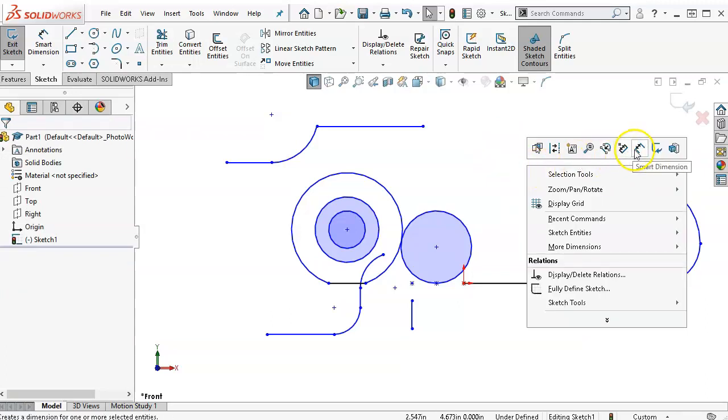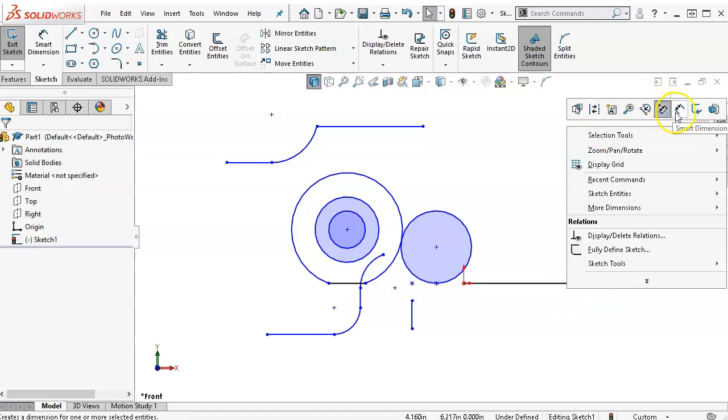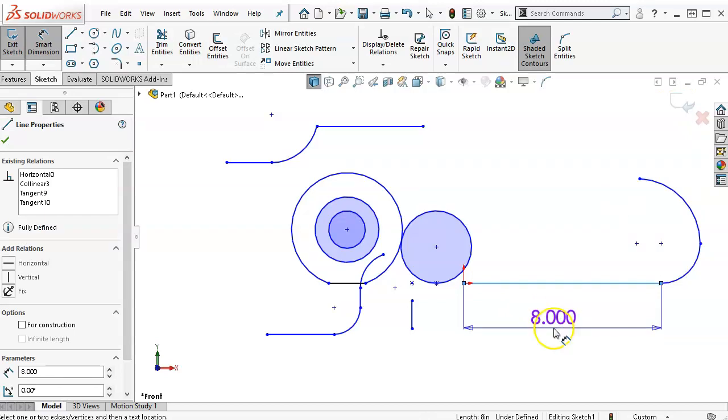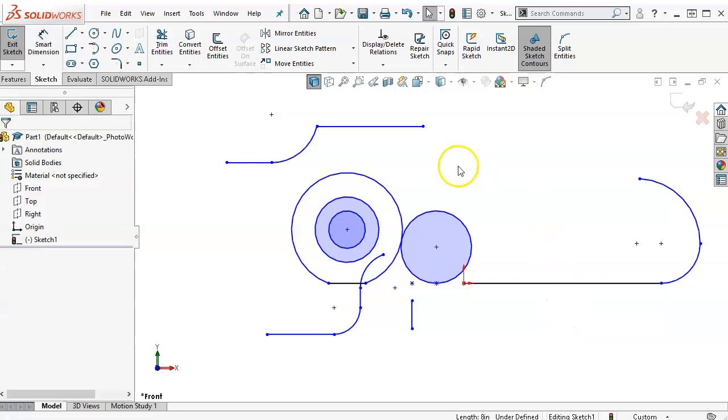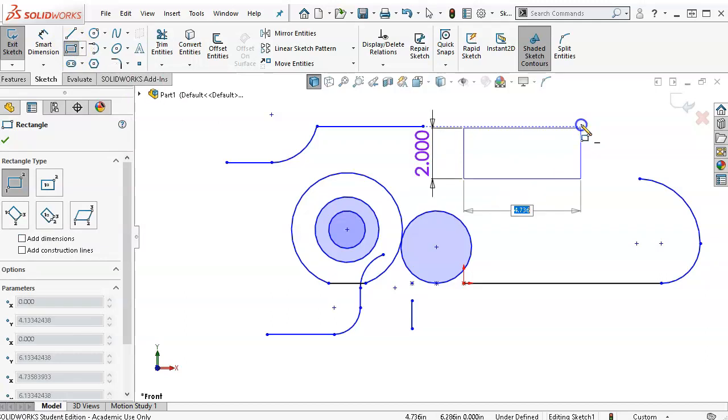It's about right. So in the dimensions, if I come over and I do sketch numeric input, then that activates the box. And then we go to smart dimension. And let's see, which one is this going to place? Oh, I'm not drawing geometry. That would be why. So if you want to add the dimensions as you draw the geometry, so in the case of the rectangle, I'm left-clicking and holding down. So the first dimension will be 2 inches, and then 4 inches.